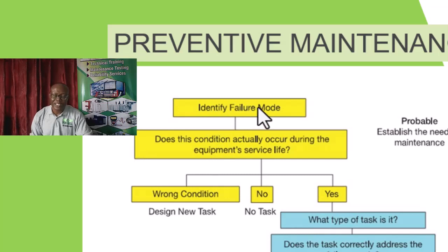Then once you have identified all the failure modes, you look at all the maintenance strategies that you have in place, and determine which failure mode that particular maintenance strategy is taking care of.